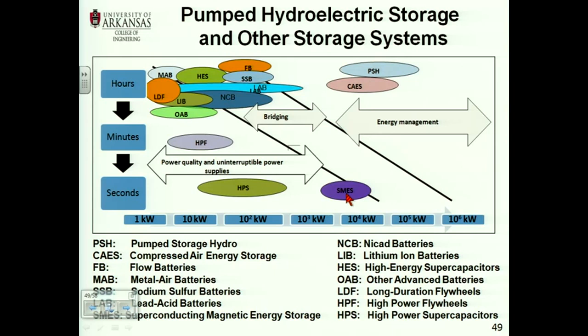Here is SMES, superconducting magnetic energy storage. Well, you can get a lot of power, but just for seconds. So the applications of these two technologies are different. SMES is used for very short momentary interruptions, where you need to have power provided for seconds.